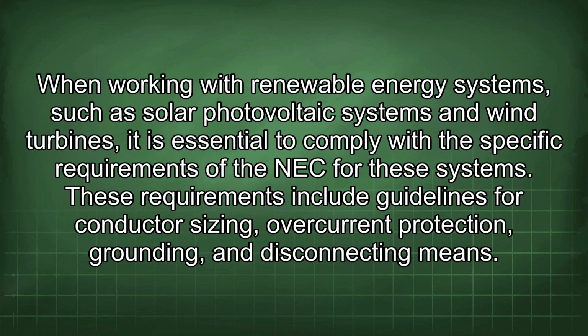When working with renewable energy systems, such as solar photovoltaic systems and wind turbines, it is essential to comply with the specific requirements of the NEC for these systems. These requirements include guidelines for conductor sizing, overcurrent protection, grounding, and disconnecting means.